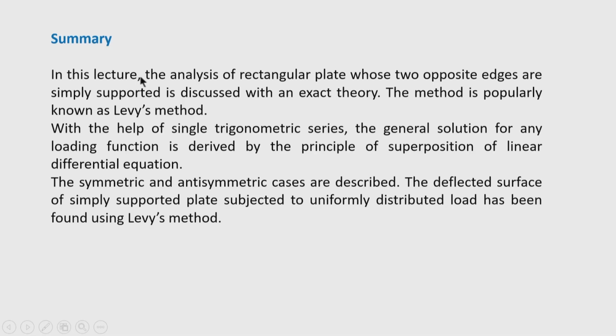So, let us see what we have done today. In this lecture, the analysis of a rectangular plate whose two opposite edges are simply supported is discussed with an exact theory, because Levy's method is an exact theory. It yields the closed form solution for the differential equation of the plate. The method is popularly known as Levy's method. With the help of a single trigonometric series, because only two boundary conditions are known, one sine function is taken in the deflected surface assumption first.